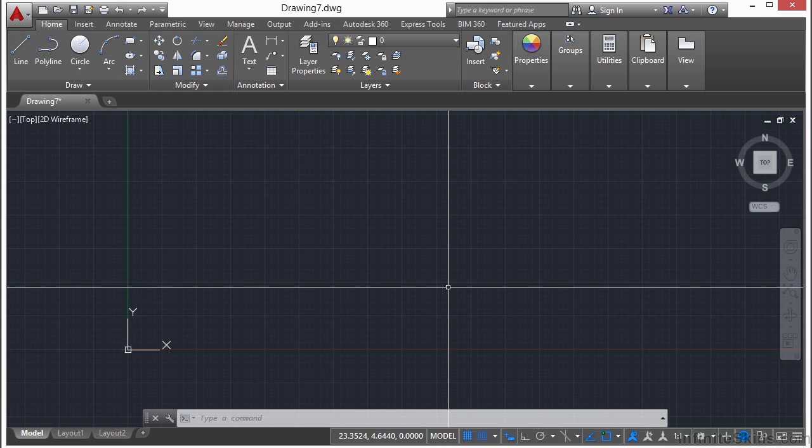An example of that might be a surveyor needing to work with a coordinate system that is offset, possibly rotated, from a specific point of commencement or some other land-based marker. This will allow the surveyor to work very easily in a coordinate system that is relative to the property boundary, but still relative to its referenced real-world coordinates. Another reason to rotate your UCS is to draw in an isometric or rotated plane.